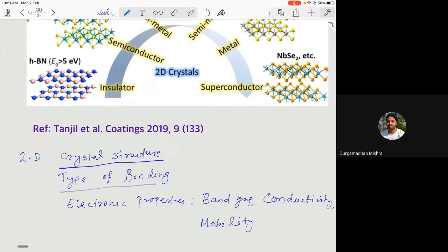I did not really discuss how the inversion that we saw, the channel, forms in the metal oxide layer. You can read about it; it is quite easy. If you read a little bit in Sze or Kasap, you will understand that we are assuming it is like a capacitor. See what the role of the electric field is: when you increase the gate voltage, what we are doing is applying an electric field across the layer.